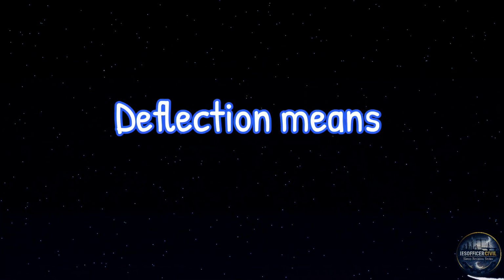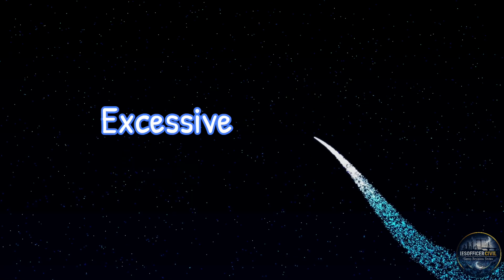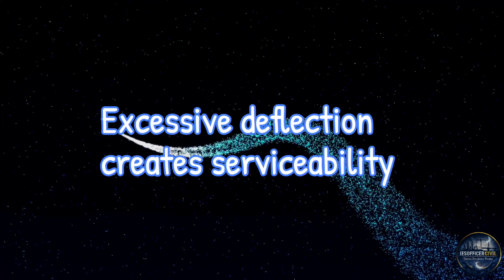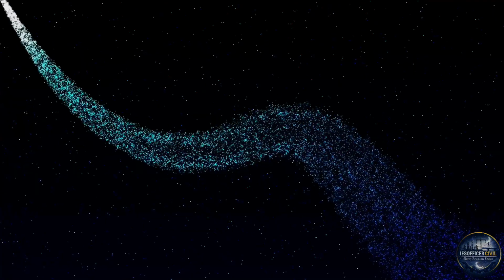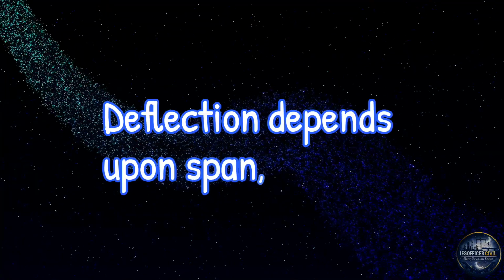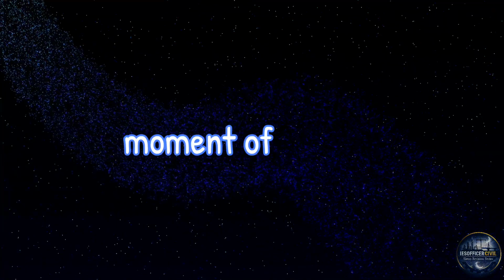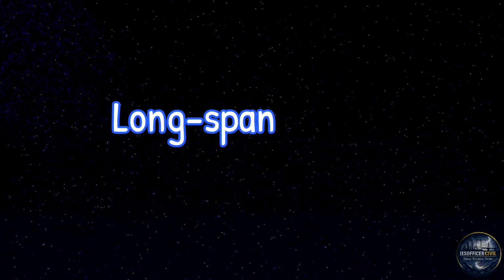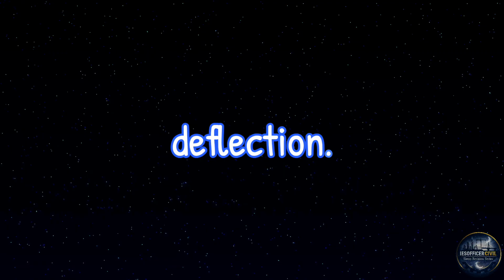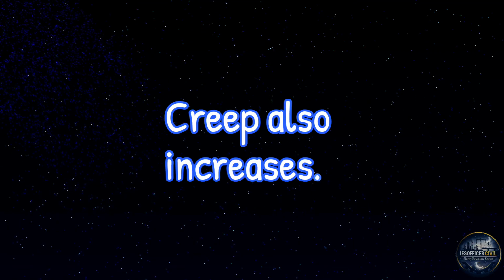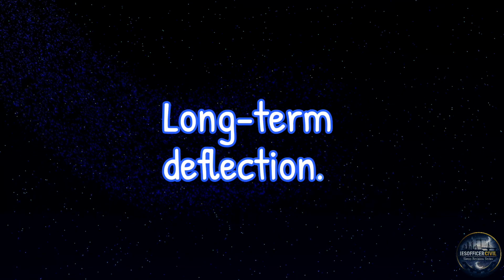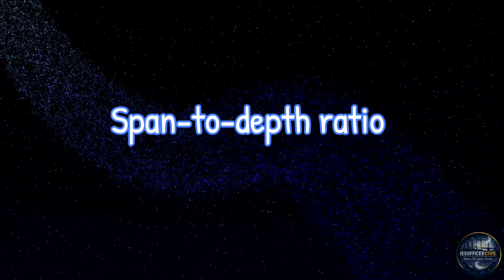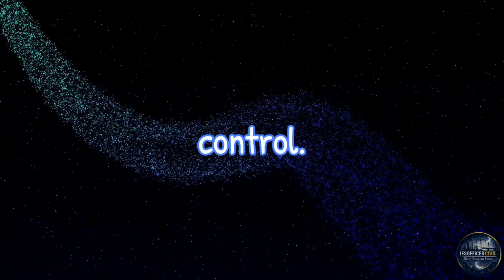Now deflection. Deflection means vertical displacement of beam under loading. Excessive deflection creates serviceability problems. Deflection depends upon span, load, moment of inertia, and modulus of elasticity. Long span beams show greater deflection. Creep also increases long-term deflection. Span to depth ratio helps in deflection control.